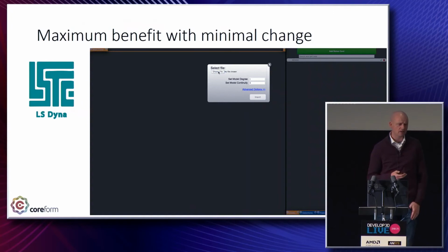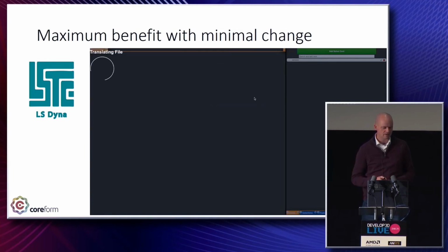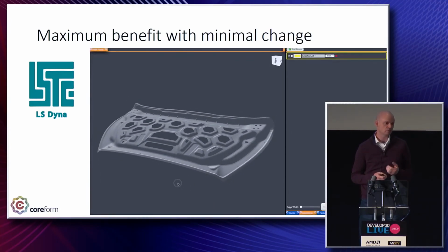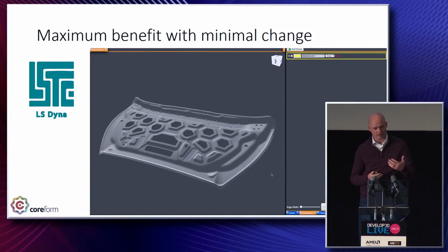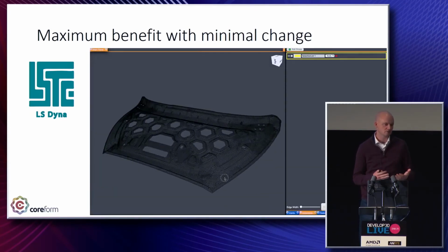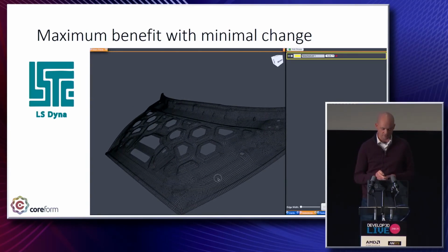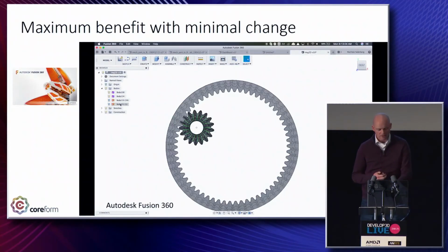We do the same thing with other mesh formats such as LS-DYNA. You can read in a car hood in this instance, convert that to a smooth U-spline, and again, run a simulation either in our solver, or we can actually export back to LS-DYNA, who's also adding spline-based capability that benefits greatly from U-splines for unstructured meshes.